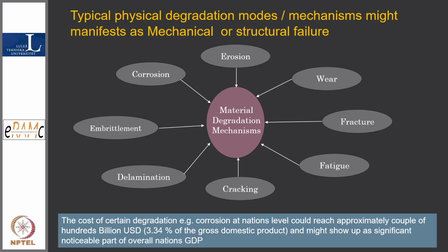So you know that in PHM we are trying to monitor degradation. Here I am talking mostly about mechanical systems. What are the degradation mechanisms that are monitored, and they require either periodic or continuous monitoring. Continuous monitoring is definitely not possible in all cases, particularly for passive systems.